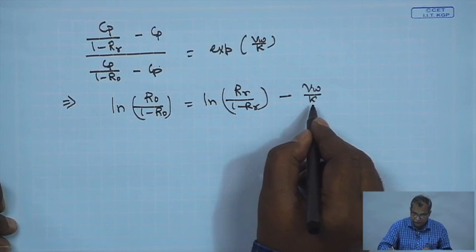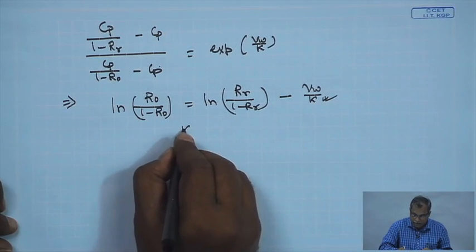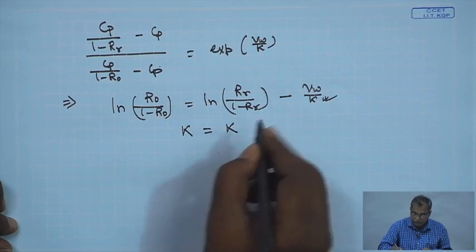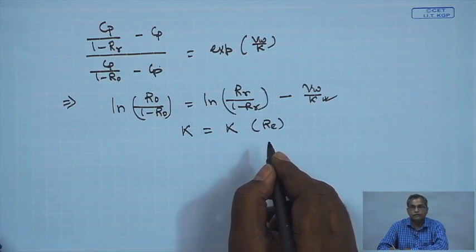Operating conditions means here we cannot change the operating conditions in terms of pressure, because the mass transfer coefficient is appearing here, and as we have already seen, the mass transfer coefficient is a strong function of Reynolds number, and Reynolds number will basically be a strong function of the cross flow velocity. So, this method is known as the velocity variation technique. What we will be doing? We will be applying different cross flow velocities in the system that will alter the mass transfer coefficient.